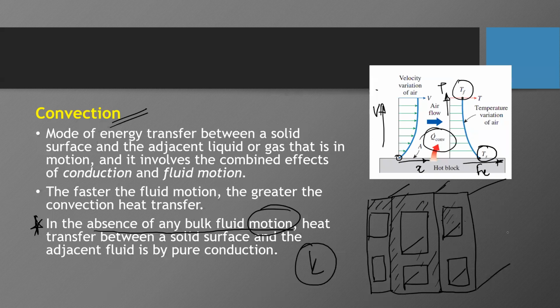When the heat is coming from outside to inside, this amount of heat transfer Q dot will go low when k goes low. So the amount of heat transferred inside your room will decrease. Then you will feel cooler than with other brick types. That's why sometimes people use this type of brick.